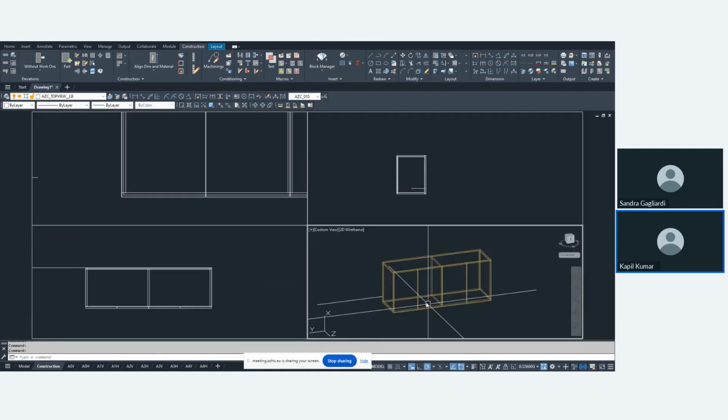So as I told you before, why I create a door panel from there, I'll go to the show edges option. See, that blue circle represents that the door will apply the automatic hinge on the left side. If we need a shutter with left side opening, but that blue circle appears on the right side of that part, then the automatic hinge will not apply in the shutter or door case. We need to always cross-check that the circle comes on the left side for a left side door, and on the right side for a right side door.